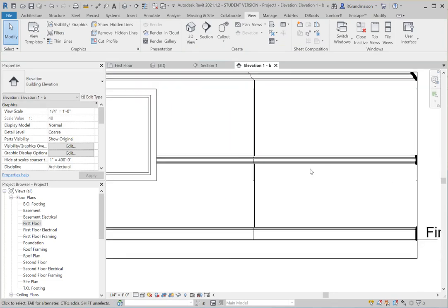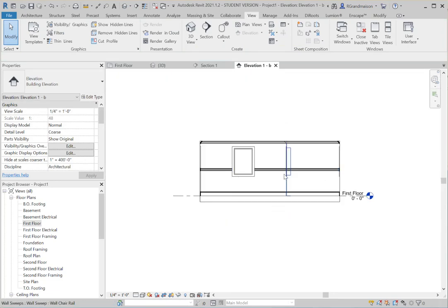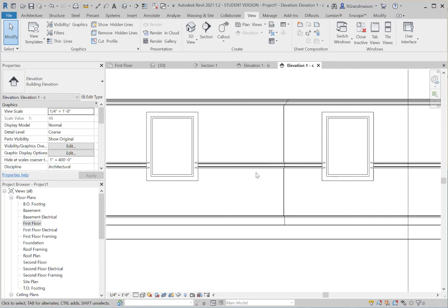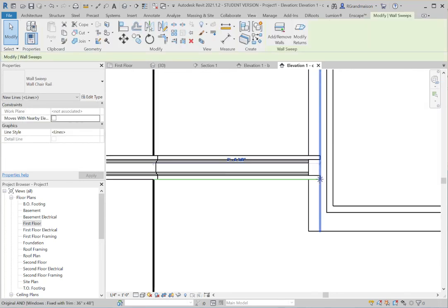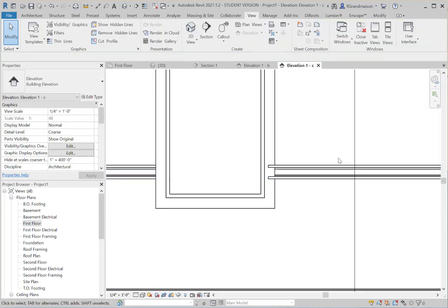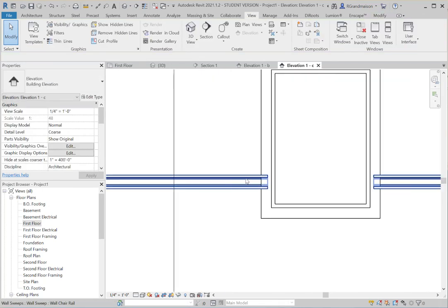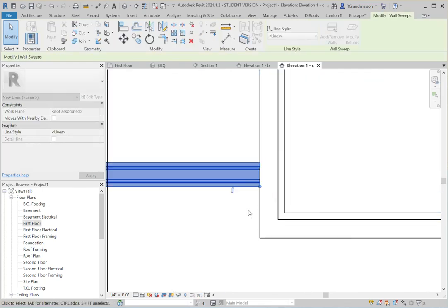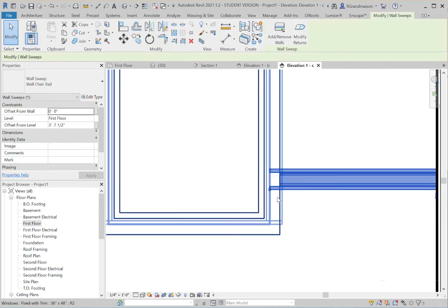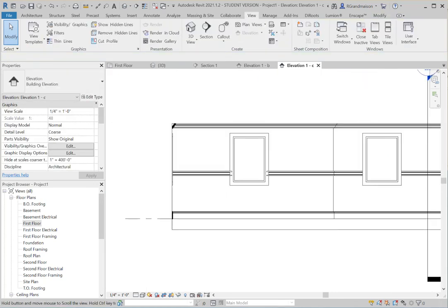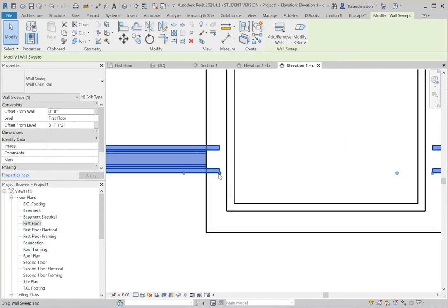When you want to work accurately, I highly recommend you actually switch to your interior elevation views. It's just so much easier to adjust things when you're in a non-three-dimensional view. Revit likes it better. It's just easier to move and adjust, and really you want to dimension in orthogonal views anyway. You don't really want to try to do that kind of stuff in a three-dimensional view.